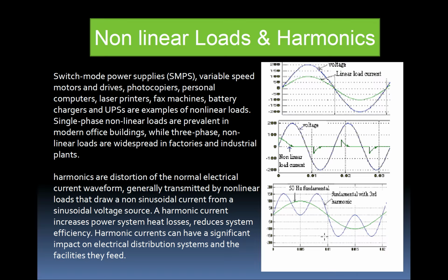In these situations, harmonics happen in our system, and the distortion itself is transmitted by these non-linear loads. The effect is the harmonic current will increase the heat losses. Therefore, when we lose our energy to heat, we reduce our efficiency.